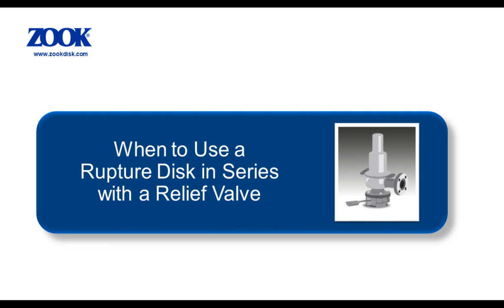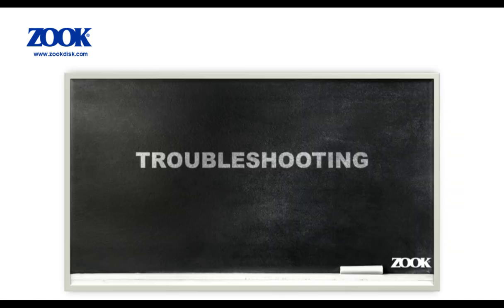A certified CCF for the specific disc and valve combination can be derived by actually flow testing. This will typically give the higher CCF, meaning a lesser derating of the combination. Caution is advised not to rely on the high certified CCF value. Doing so will limit flexibility if changes of the rupture disc or pressure relief valve are required in the future.